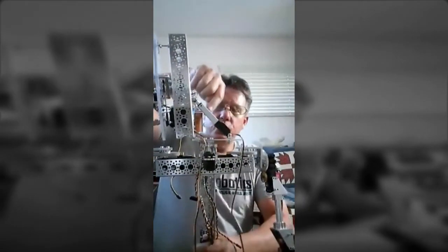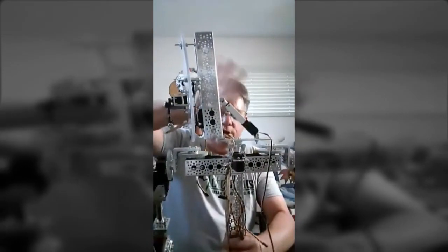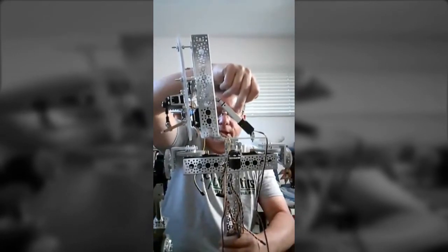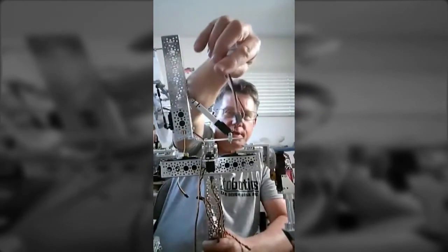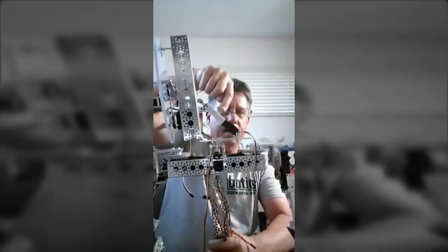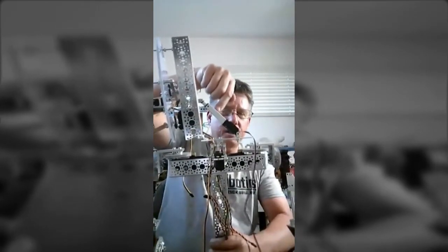You can use a servo for this, but a lot of times you get a lot of weight up here on the front end with a big mask, and it takes a tremendous amount of torque back here to get your nod back and forth. So I really like these little actuators. These hook in just like a servo does. They have feedback just like a servo. They fit into our controllers. And I'll tell you, you will have no problem with torque on your nod here.